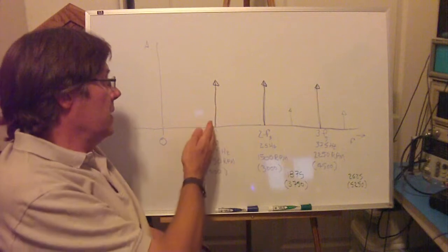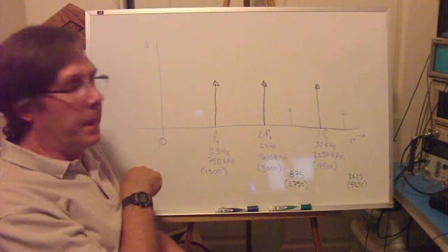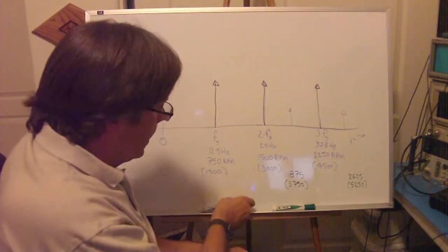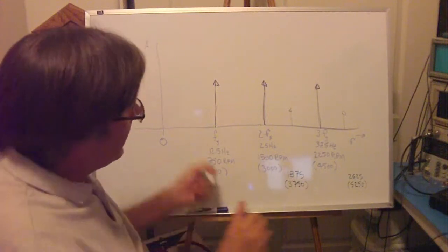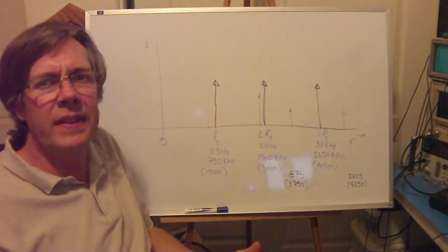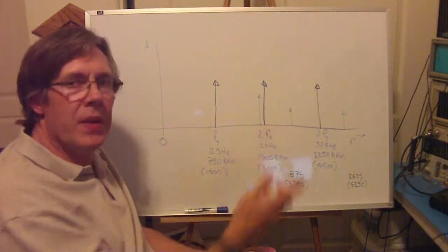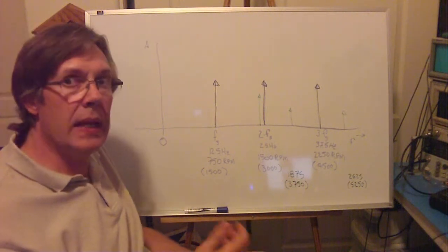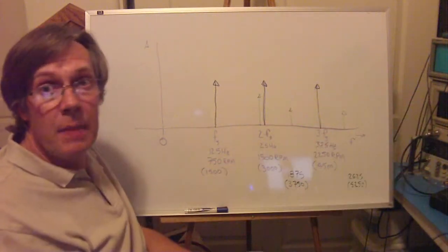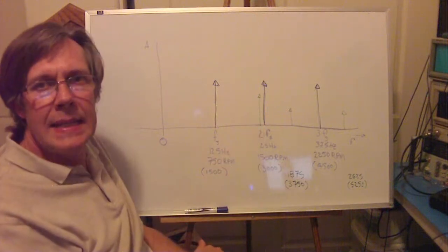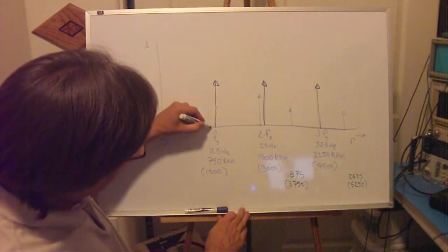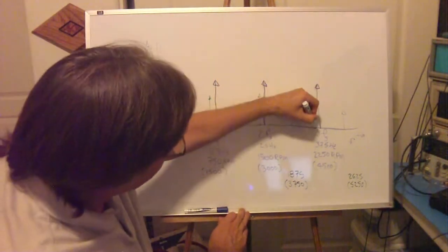And as we mentioned before, if it's a little bit less than that, it's going to look like it's rotating backwards. So say that we could rotate the rotor at, instead of 1500 RPM, let's say, for example, 1450, or 50 RPM less than this multiple of the sample frequency. What we would see is we can't tell that frequency. Again, we can't tell when it looks stationary whether it's really turning at some multiple of the sample rate or not. When it's 50 RPM less than the 1500 or any one of these multiples, we can't tell whether it's here or here.